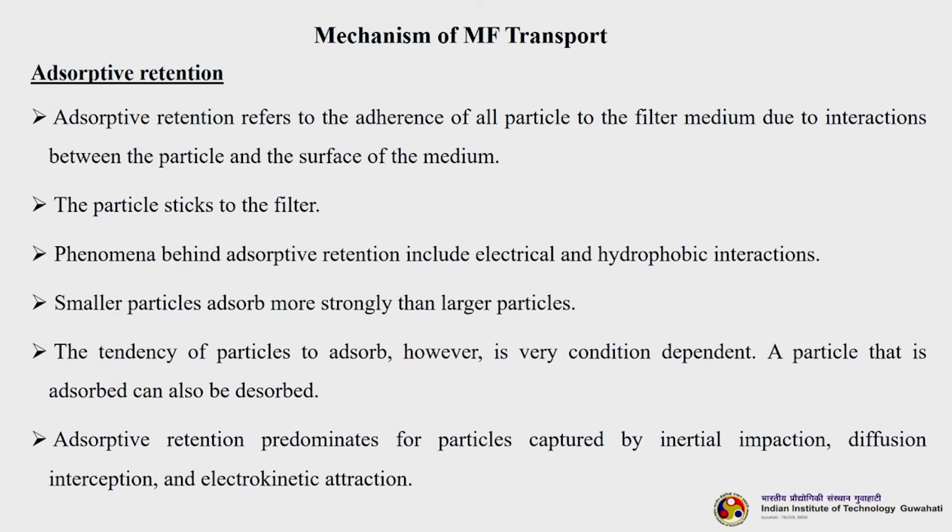The next one is adsorptive retention. Adsorptive retention refers to the adherence of particles to the filter medium due to interactions between the particle and the surface of the medium. Basically, you can see on the surface of the membrane they are getting deposited; the particle sticks to the filter. The phenomena behind adsorptive retention include electrical or hydrophobic interaction or even both of them. Smaller particles adsorb more strongly than larger particles, and the tendency of particles to adsorb is very condition dependent. That means a particle that is adsorbed can also be desorbed once the condition or the environment changes. Adsorptive retention predominates for particles captured by inertial impaction, diffusion interception and electrokinetic attraction.